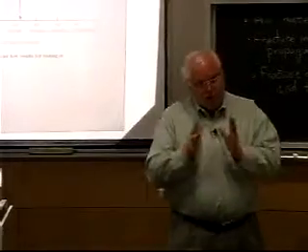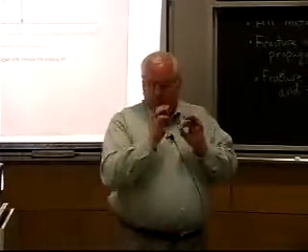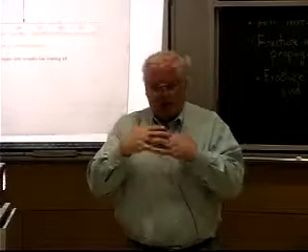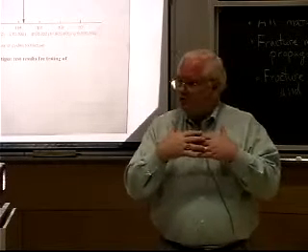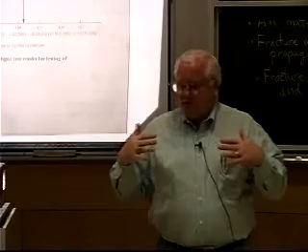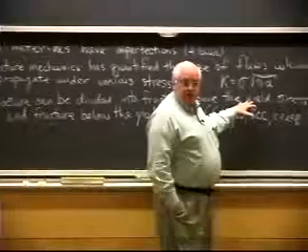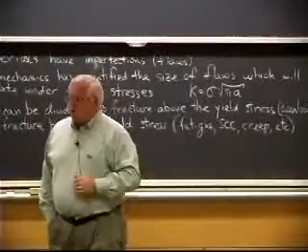If you look microscopically, when you're vibrating out here, you find microscopic little regions where the dislocations in the crystal will start little flaws. And you are actually creating little notches, and those little notches get to be bigger notches. As they get bigger, fracture mechanics tells you that the stress intensity increases. If the stress intensity increases, that crack is going to start growing faster and faster.